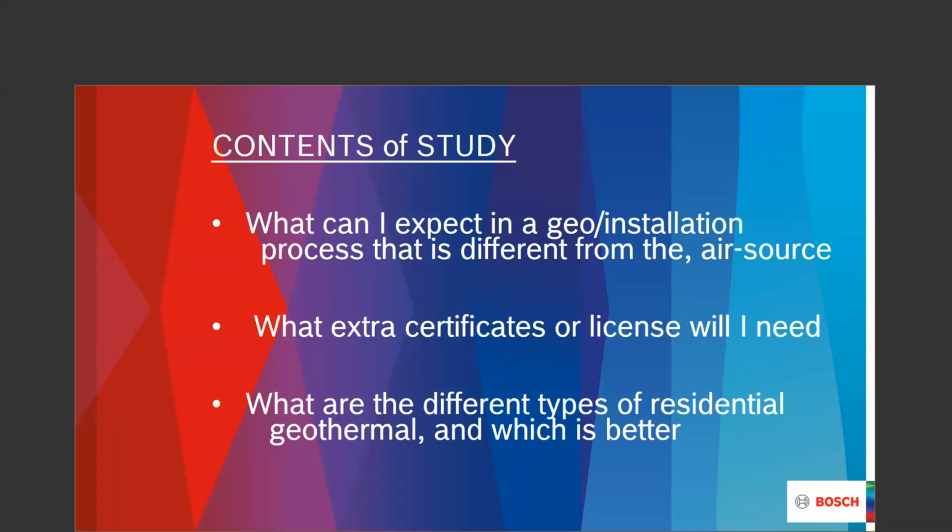It's a package unit. It sits inside the structure, and it is basically bought in two different ways. It's a copper nickel or a copper type coax. And so we're looking at either an open loop or a closed loop application. An open loop is something where we take Mother Earth's water out of the ground. There's going to be some type of auxiliary pump that takes that water, runs it through my coax, and then disposes of it somewhere.